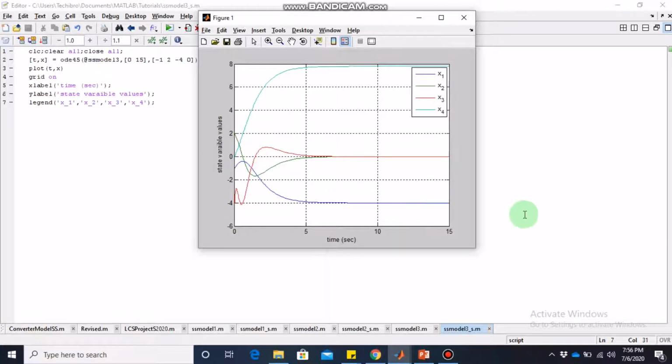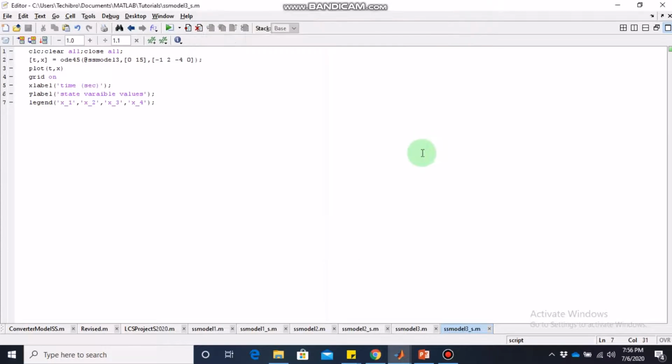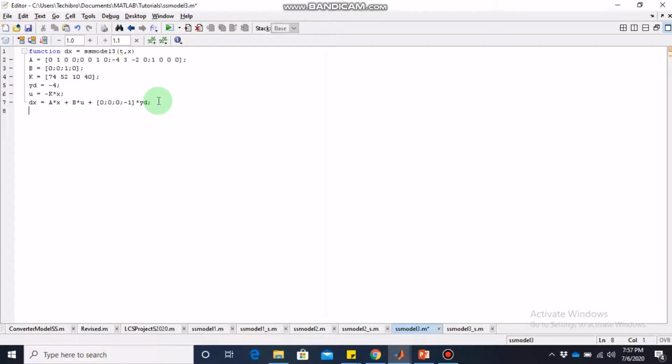And now we come to the point of today's lecture: how do we incorporate the state observer in this integral control. So notice that the original system that we had was a 3 by 3 system. Let us suppose that the output that we have is x1. So we are measuring x1 using the sensors, and if the output is x1, then we have to estimate the remaining 2 states, x2 and x3, using the Luenberger observer. If I add the dynamics of the Luenberger observer, it will have 3 states of its own, and those will be the estimates of x1, x2, x3.